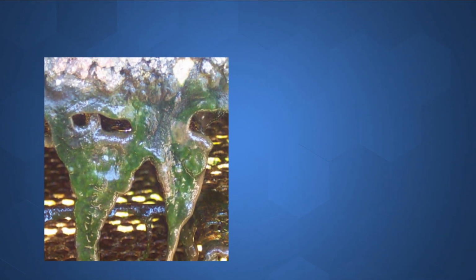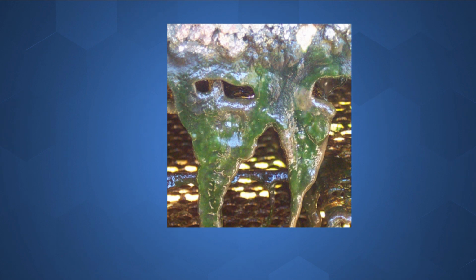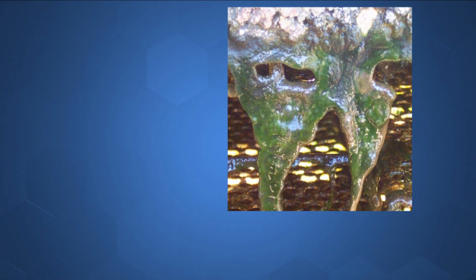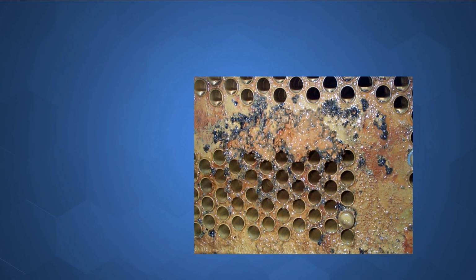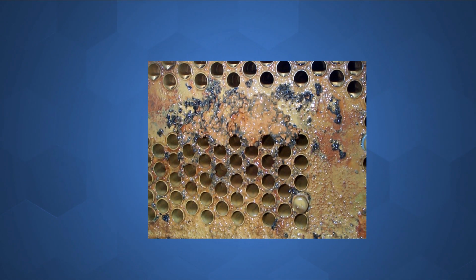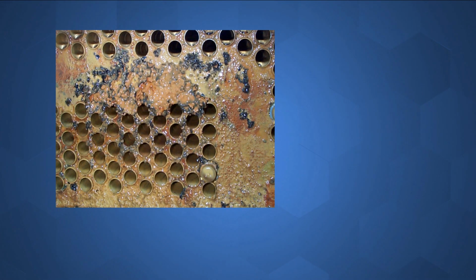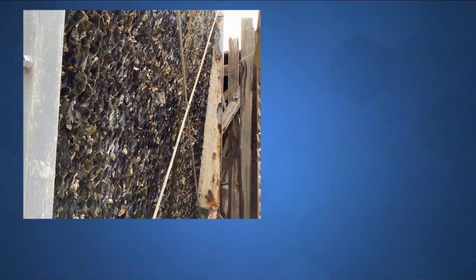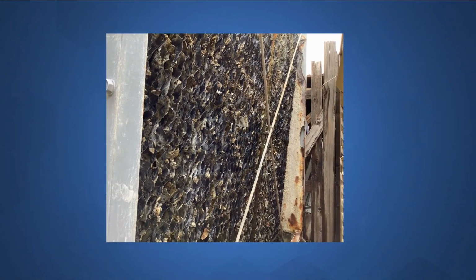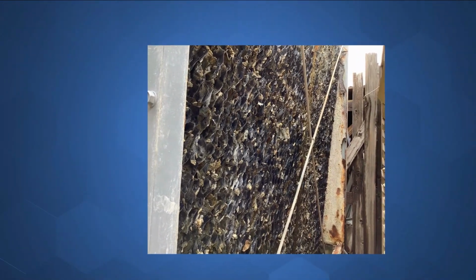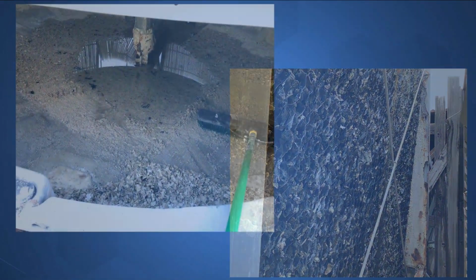Over 80% of water treatment business is won or lost on the efficacy of the biocide program. Proper biocide programs help prevent system failure and damages caused by microbiological growth. If allowed to grow unchecked, microorganisms can cause severe corrosion and slime deposits in the water and shut down a system overnight. Cooling towers are particularly susceptible to microbiological growth since they provide ideal conditions for growth of problem-causing microorganisms. Furthermore, if the conditions are right, disease-causing bacteria such as Legionella can thrive in a cooling tower.